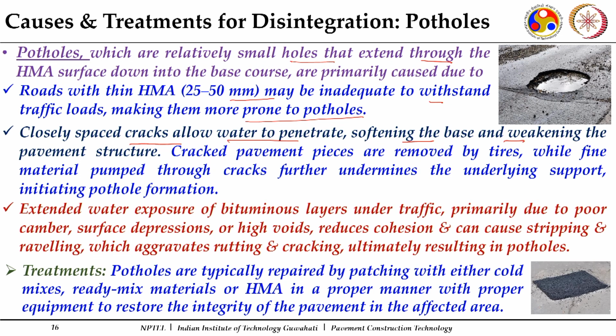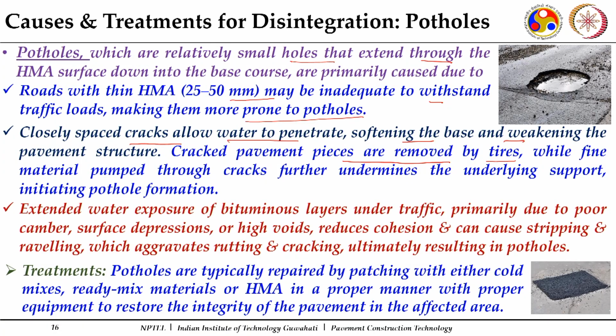So, the cracks get more widened, and in due course of time, because closely spaced cracks will be formed, these cracked pieces are going to be picked up by tires. Along with it, since water has gone into the underlying layers, fines will start coming out of it, and this creates a loss of support from the underlying layers, finally initiating the formation of potholes. So, this is an accumulation of factors which starts with small depressions, small cracks, and then ultimately leads to the formation of these potholes.